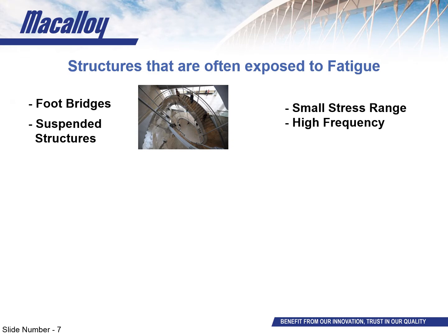Now, the reason the stress range experienced is so small is the fact that that cyclic load is very small relative to the dead load. So that means that the change in load in the material, and therefore the change in stress in the material, is small. And that means that it can often be considered as quasi-static.